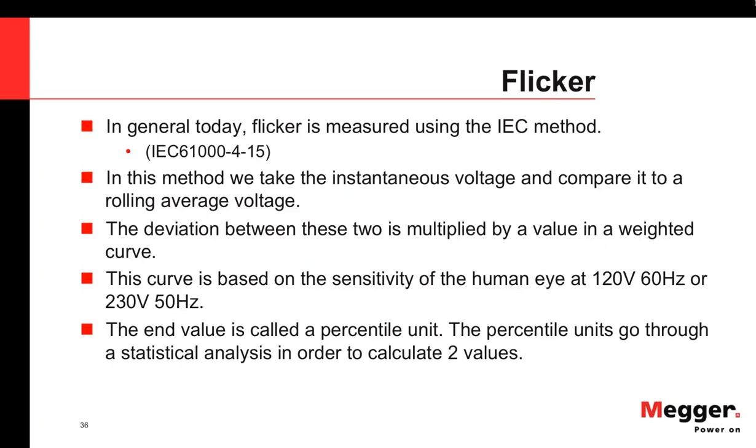But because of this, we were able to come up with a flicker measurement using what we refer to as an IEC method, IEC 61000-4-15, which has now been adopted by IEEE 1159. And this method,